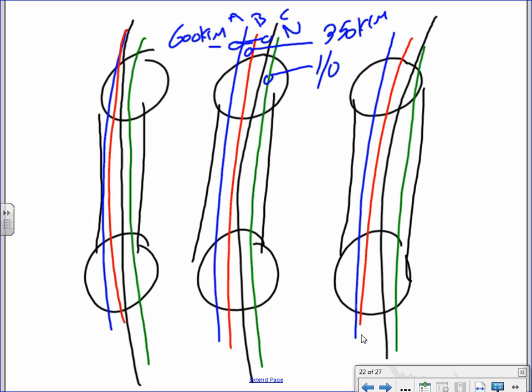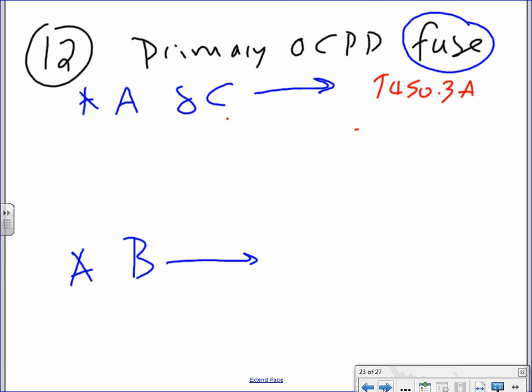Can you see that? So the 2 phases, phase A and C, are the same size, B is different, and neutral is different when you size your conduits. Cool? Any comments, guys? Any questions? So that's probably the hardest one to understand. If you guys are good with that one, let's go to the fuses.